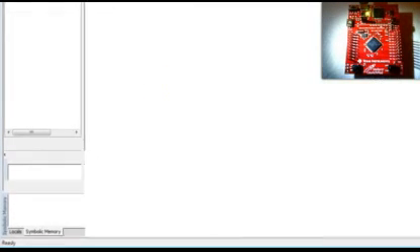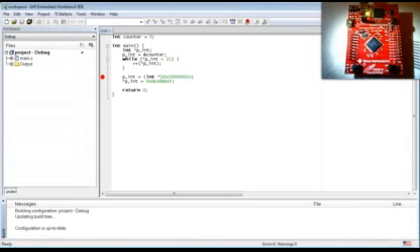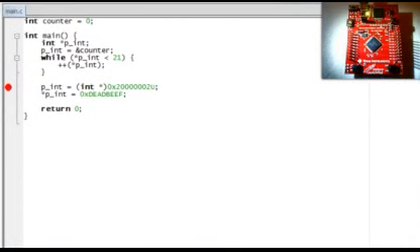The heavy lifting is really over, because coding this all up in C will be a piece of cake. All there is to controlling the LED boils down to writing numbers to specific memory addresses, and this you already know how to do with pointers. Specifically, you are going to use the pointer hack that I showed you at the end of lesson 3, because this technique allows you to write any number to any memory address you choose.